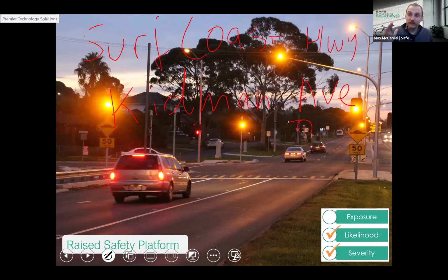And the steepness of speed humps on local streets is very significant. If you implemented that on arterial networks, every bus would be bottoming out, and you'd just be having lots and lots of rear end crashes. You'd also have potentially vehicles that would actively search for those speed humps so that they can get up and get some air and things like that. So there's lots of reasons not to implement something that's too steep.